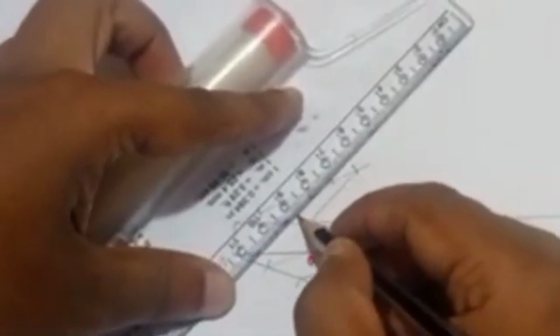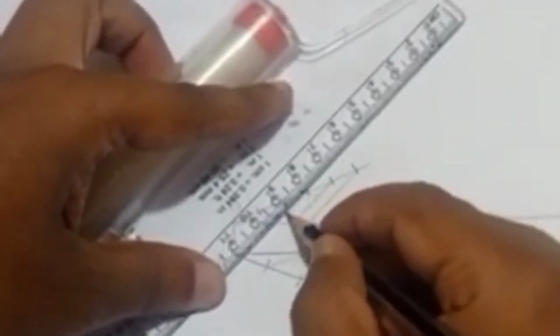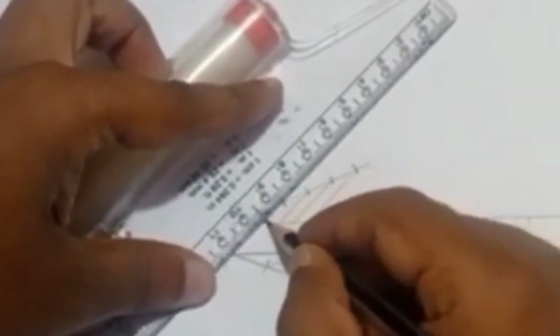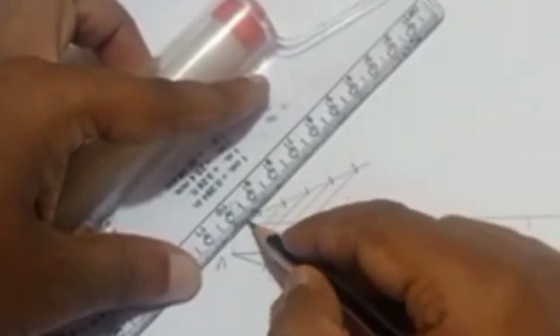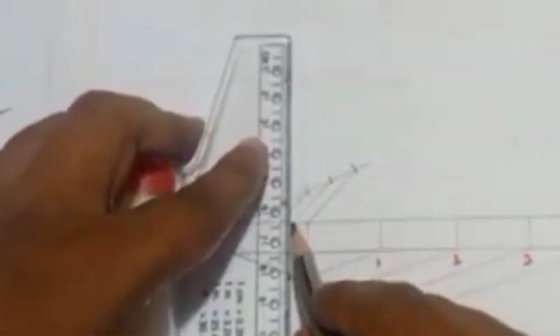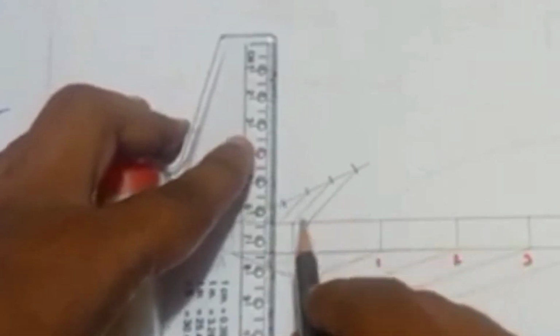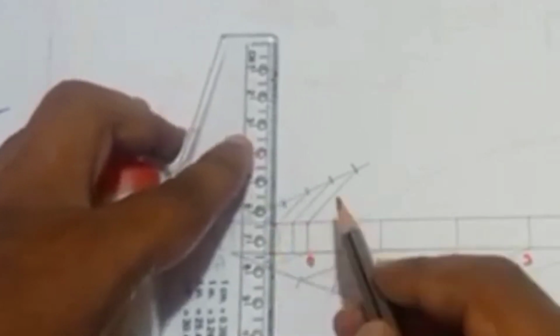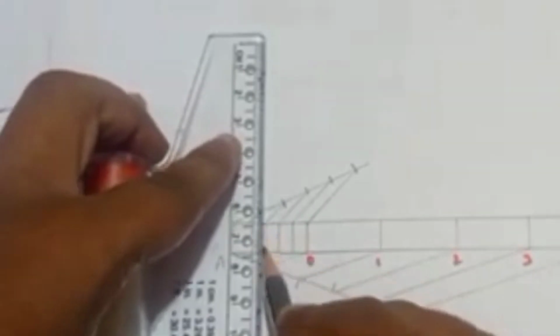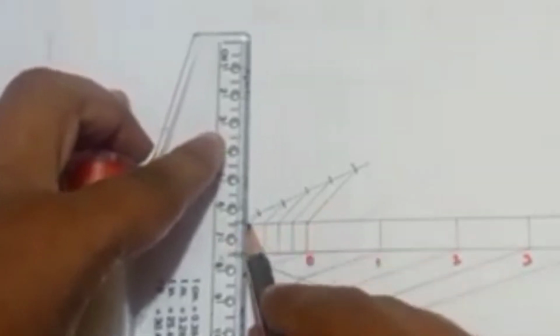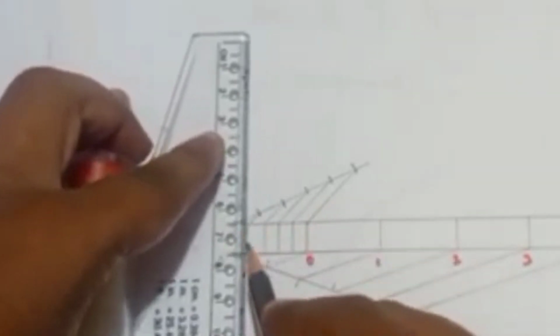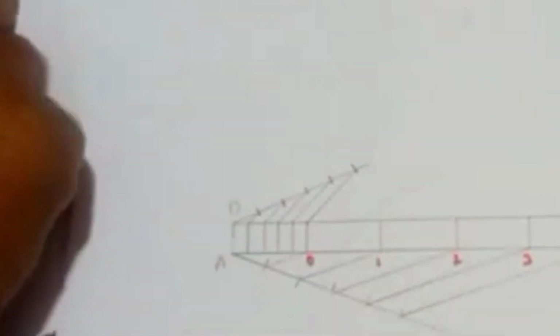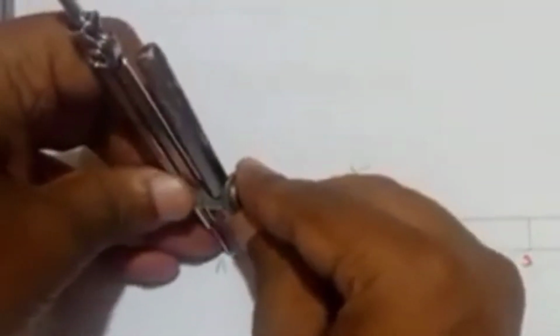Okay, now using the roller scale draw the parallel lines. Okay, now you can draw the vertical lines where you have connected. So it will be divided into 5 equal parts. Now measuring one length here, in same way we can divide the remaining boxes into equal parts here. Okay.